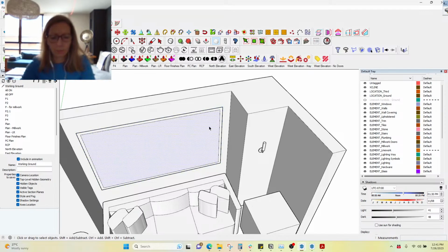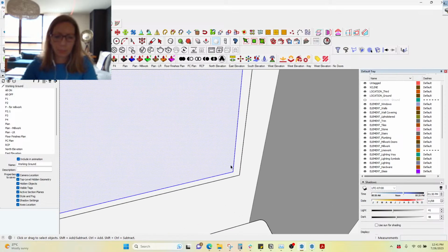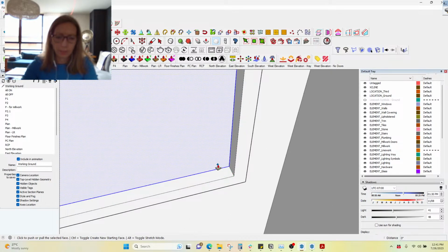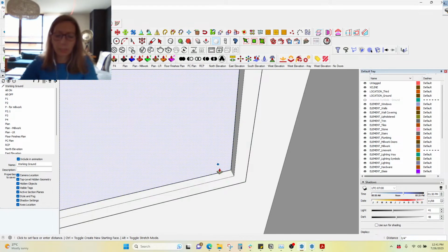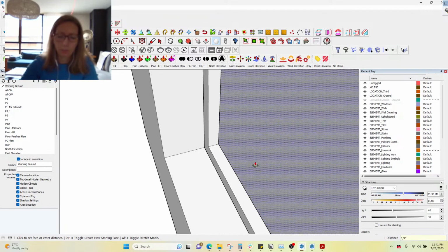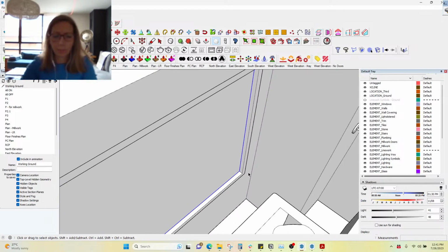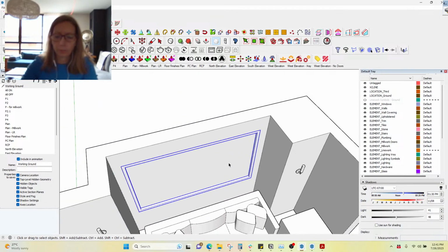And then I will copy that inner part for the glass later, group that. So I've just grouped the frame, and now I'm going to paste in place the sheet that can be the glass. Then I moved it into the center, and I'm going to offset it for a push-pull on both sides, and then group that together. Now I group the frame and the glass together, so now I have a quick window assembly.